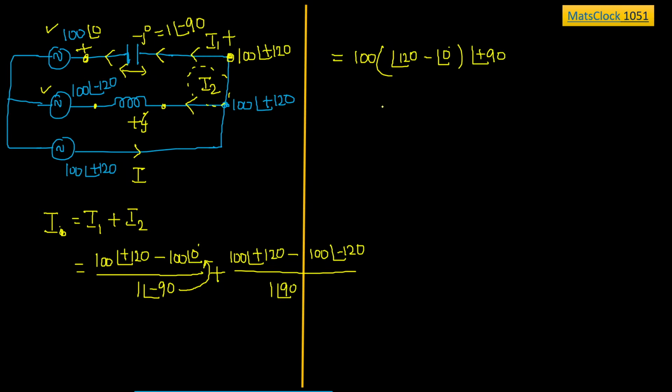The term that is coming from the denominator. And 1 is 1 only, you can leave it, right? We need not give importance to that. Let us continue anyway. And here also, if we take 100 outside, in the bracket you will have plus 120 minus the angle of minus 120, and with this we are going to add one more minus 90 degree, which came from the denominator. Now let us expand it further.